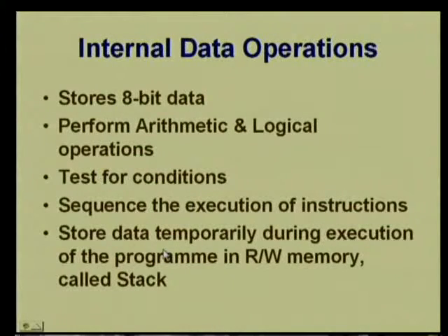The programmer will predefine which part of the read-write memory he is going to use as a stack whenever it requires. The starting address of that read-write memory, from where he wants to use it as stack, is stored in another register known as the stack register.